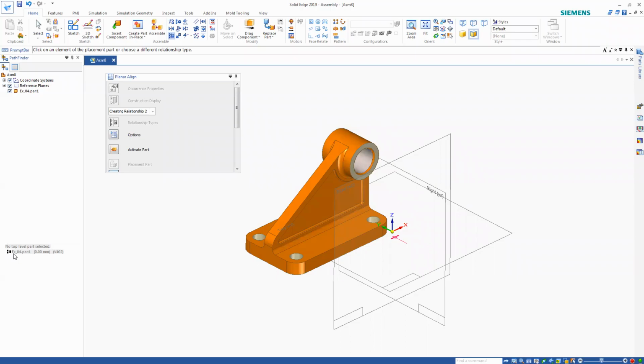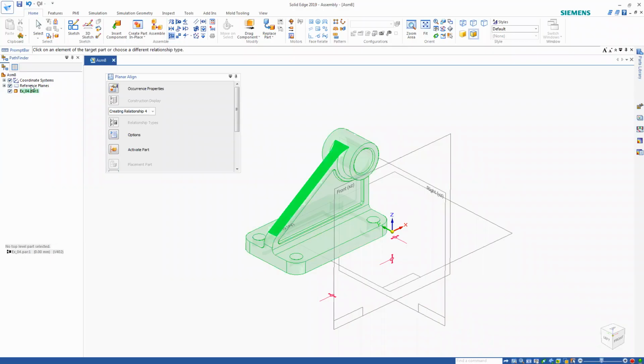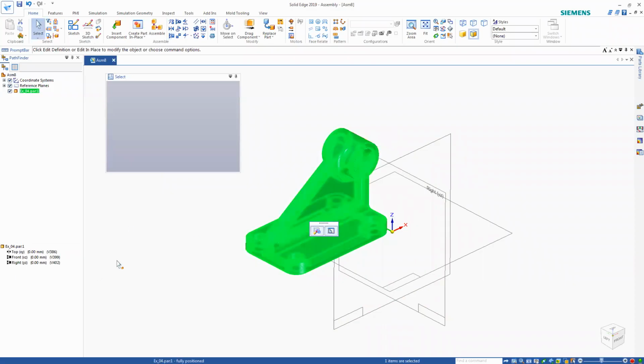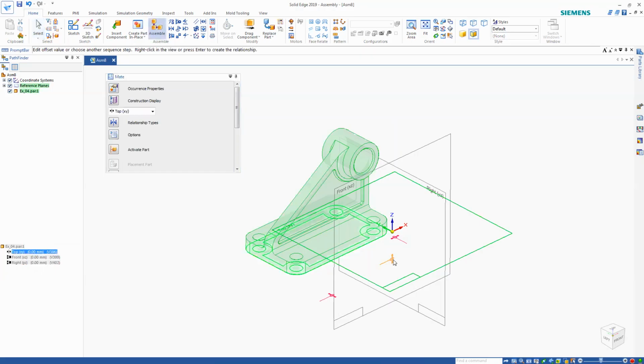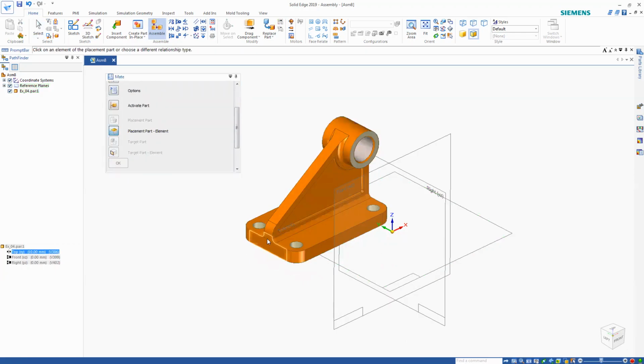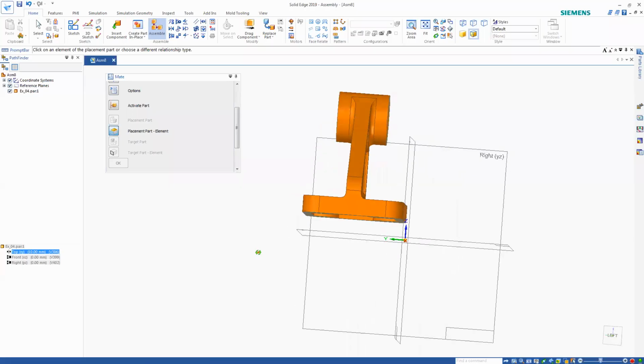You see the relationships over here. Right? If you select this part, now you'll be able to see several of them. These are relationships. You can see even the distances are over there, and even a variable is defined for that one to define the distance. Say suppose I want to change that one. Here it is 0. See whether I can change that one to some value. Offset value here. If you say offset type, I'll say something like 10, see whether it is possible. It's moving. So I can define a certain distance away from that one. You see, that's also possible.